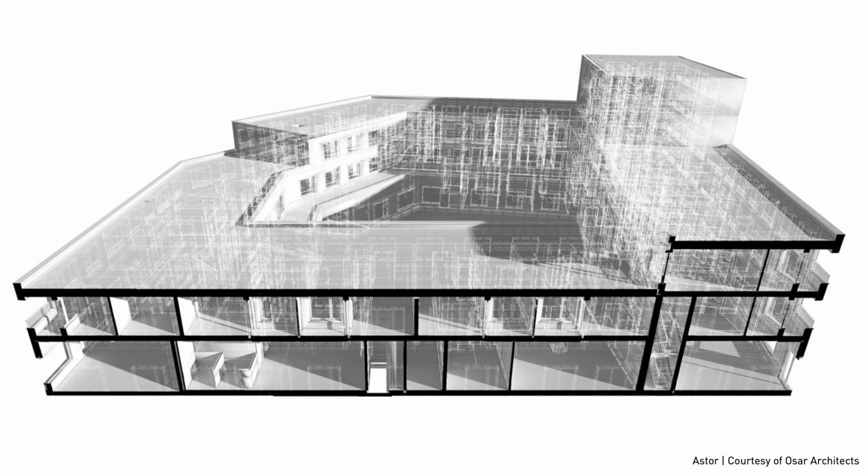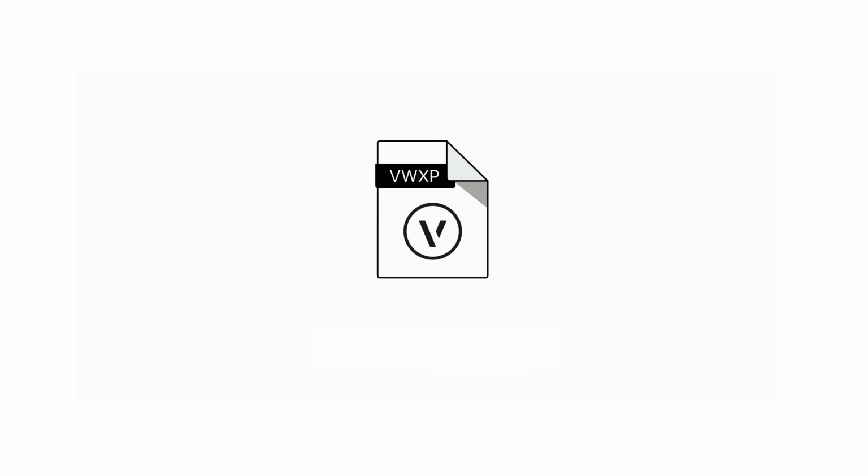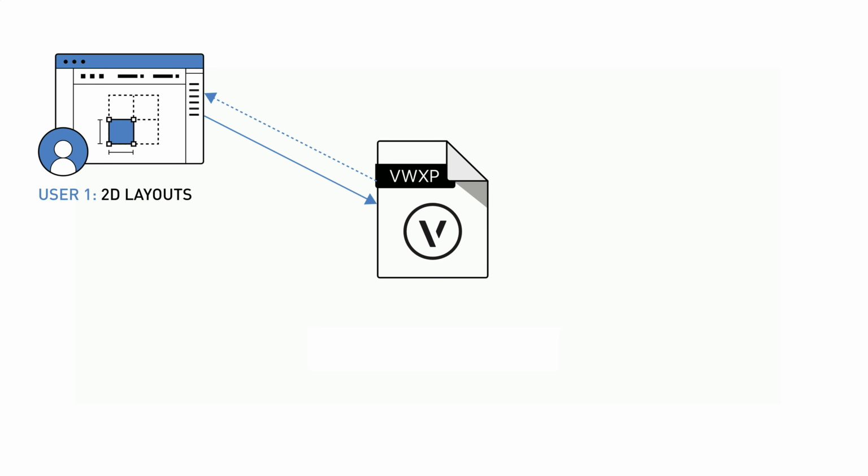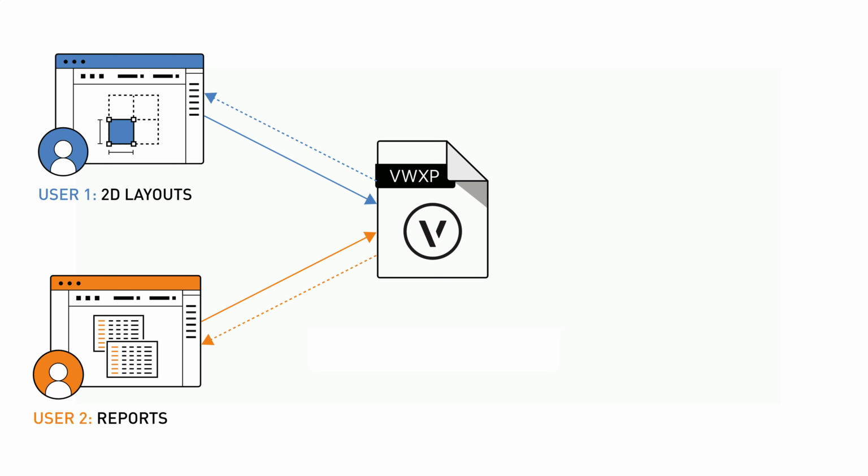And if you have a team of people who are tasked with working on that BIM, I propose using a multi-user environment. This allows you to have one single project file for the entire project. The project file is essentially a regular file, but with special permissions and abilities enabled to allow multiple team members to check out and work on parts of it as needed. When each team member opens the project file, a special working file is created in which they can get their work done. Once they have completed an amount of work, they can synchronize their changes back to the project file